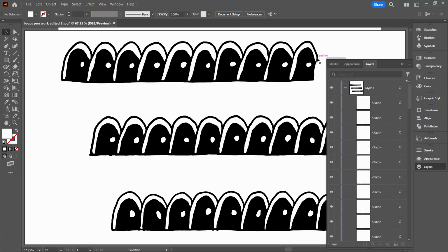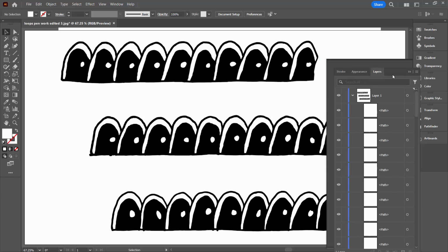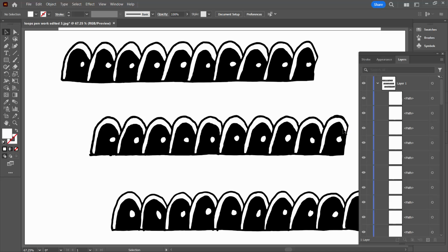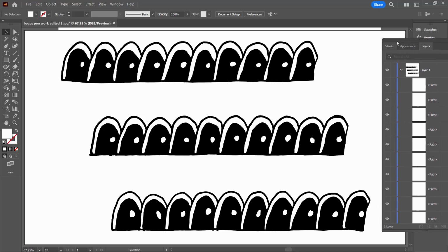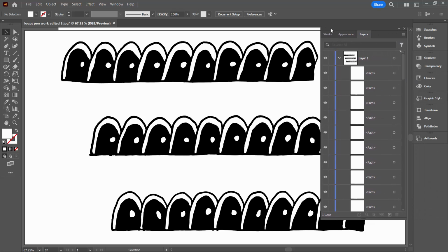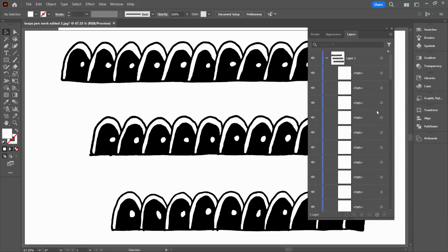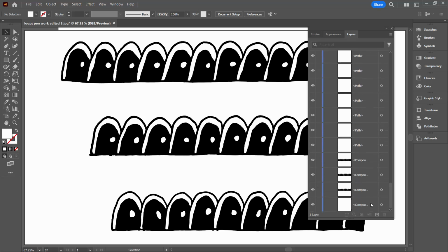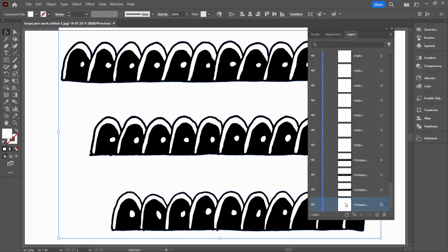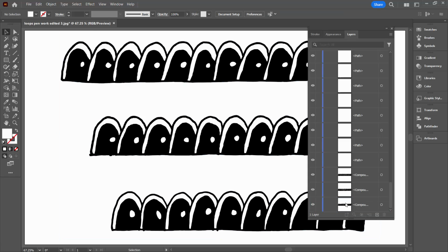And you'll see here on this end that when I drew these, I drew this end piece in. So this would be traced as a white object. Now that's really important in case you want to color this again later on. So once you've expanded this, you're going to go to the very bottom, because the very last object here is the background. So you're just going to select that and delete it.